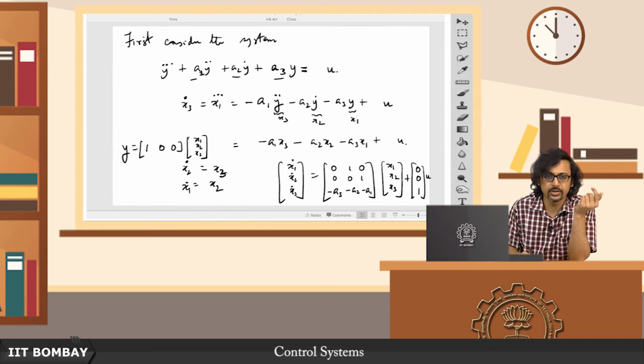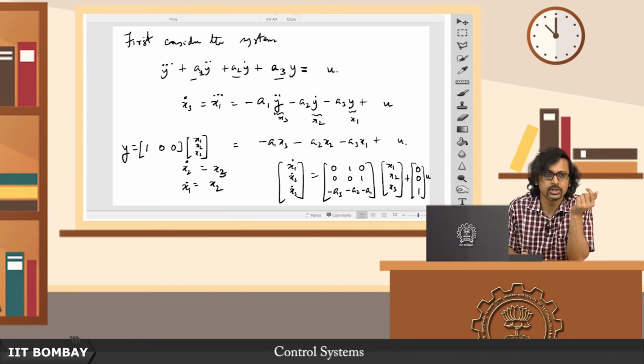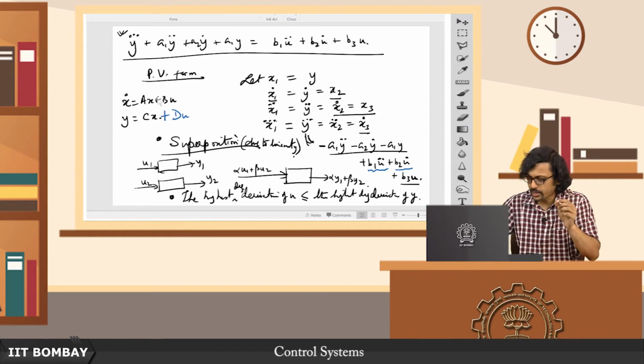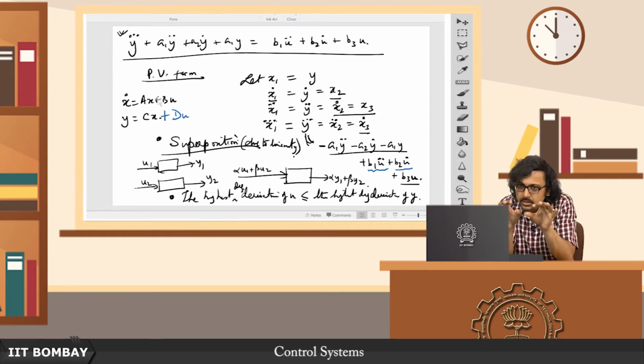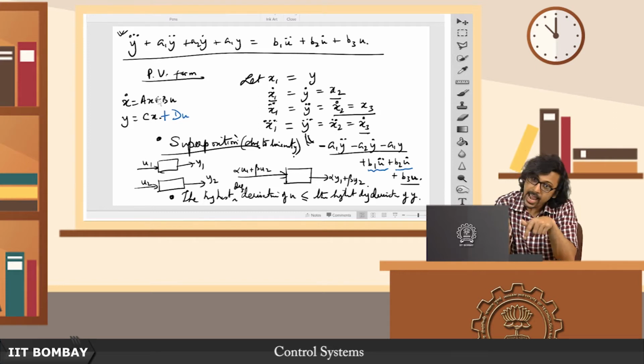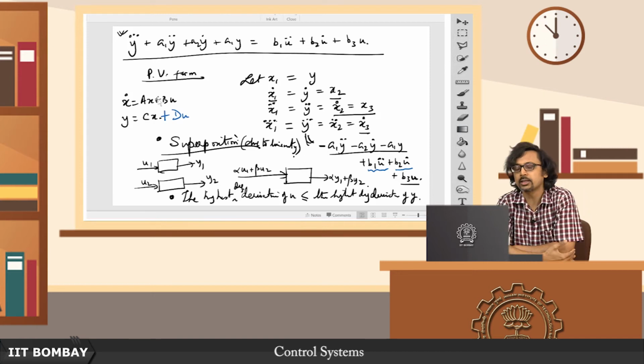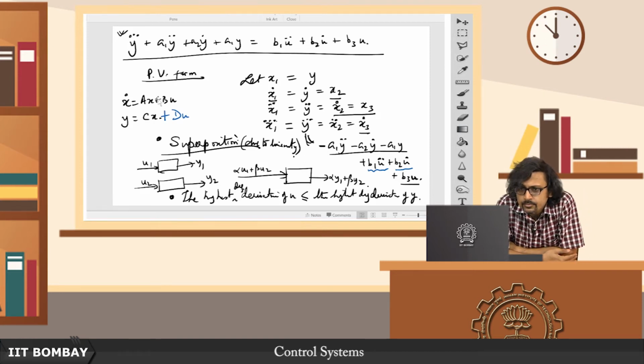See, in this original ordinary differential equation, the input is u, the output is y. But now I am trying to take it piece by piece, and the hope is that if I understand what the response due to u is, I should then be able to understand what the response due to B3 times u is, and by extension, and this is the beautiful thing, I should also be able to tell you what the response due to u dot is.